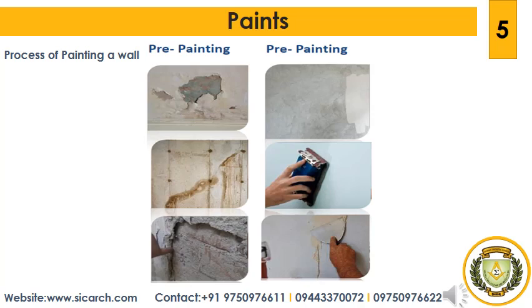The next is patent knotting. This is also applied in 2 coats. For both the coats, the varnish prepared by dissolving shellac in methylated spirits of wine is used. And the third type of knotting is lime knotting. The knot is covered by hot lime and it is left for 24 hours. The surface is then scraped off and then ordinary knotting is carried out.